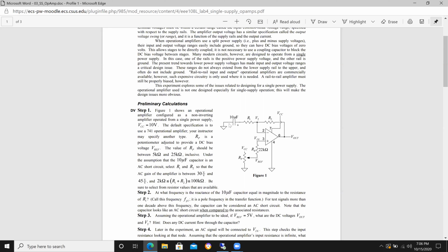So that's one of the major reasons we had this capacitor in back here: we disconnect the DC gain of the circuit. Now, why would you want to do that? Well, let's imagine this is an amplifier for audio gain, right? We can't hear DC, but we hear audio.